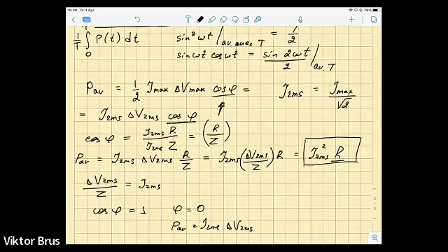So that's why next to an electric power generating facility, quite often some powerful big capacitors with adjustable capacitance are attached in order to optimize the loss factor, this cosine phi, and keep it as close as possible to unity in order to get the maximum average power distributed all over this electric circuit.